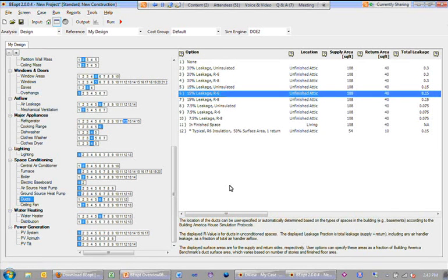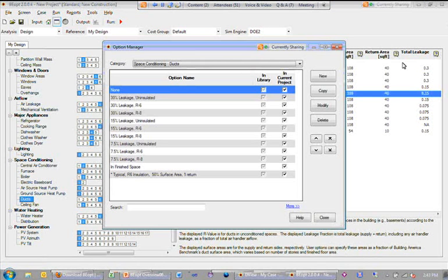So the total leakage, that fraction, represents the fraction of the supply air flow rate that the fan sees that leaks out to the outside. If you look at the detailed simulation variables here, we separate it out by supply and return leakage, and also by duct leakage and air handler leakage. But it's total leakage, you don't really care where it goes. Well, depending on where your ducts might be, in a different location than your air handler, that's why we account for those separately. Right.